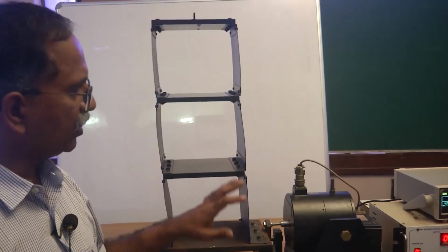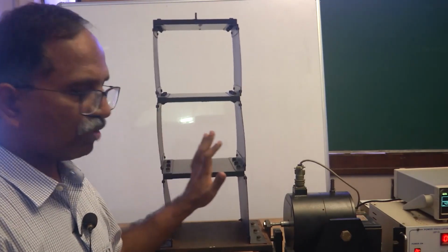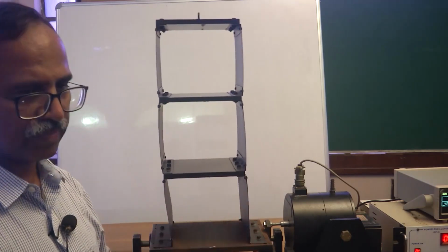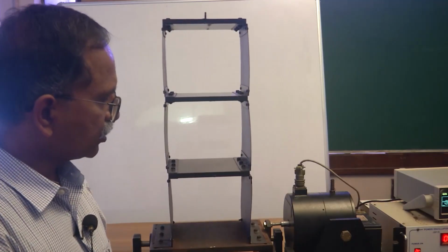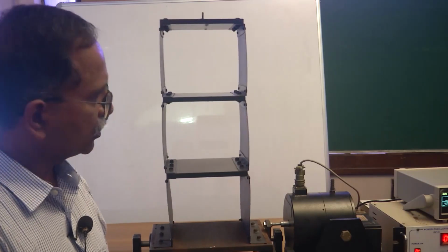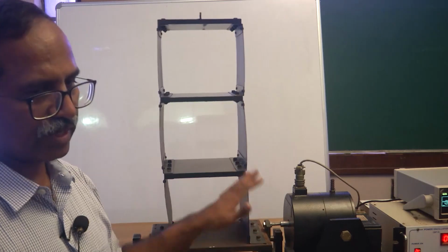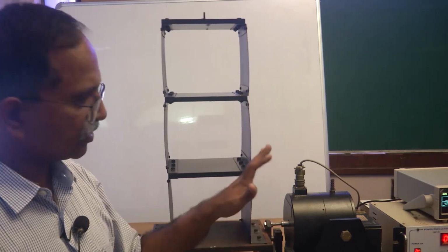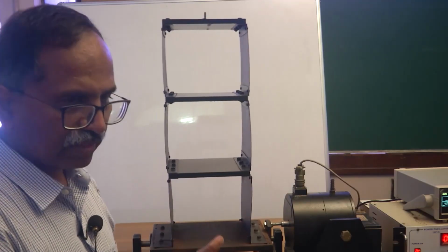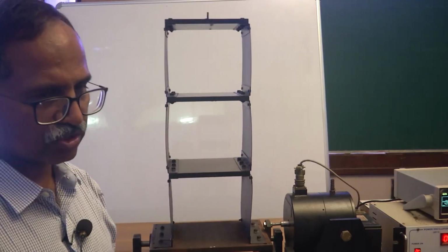All right. So what we have learnt here in this experiment, we have seen the mode shape in action. It is not by exciting the vibratory system with an initial condition matching the mode shape and the subsequent vibration at the natural mode, but we observe the mode shape by exciting the system at its resonance, and for that we excited the base of this building with a frequency that matches with either the first mode natural frequency, the second one or the third natural frequency. And when it is excited into resonance, at resonance we observe the displacement pattern, which is actually the mode shape.